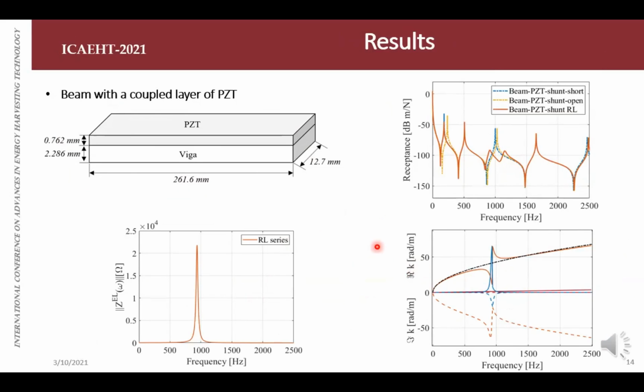The attenuation effect is similar to the effect of a dynamic absorber and occurs exactly at the frequency of the impedance design. The dispersion diagram shows the attenuation effect in the transversal mode and the longitudinal mode, respectively.